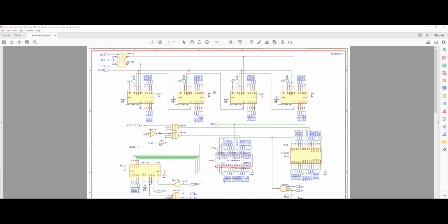It's going to happen in 2 cycles, and we're going to read a total of 16 bits into our bus. And that's basically happening when we actually want to set an initial value into our counter. So let's say we want to start from a specific memory address, and from there we want to count up. So we set that on the bus, we read it into our register, and now our register is ready to count from that address and progress into the next memory address and so on. So I guess that part is quite clear, right?